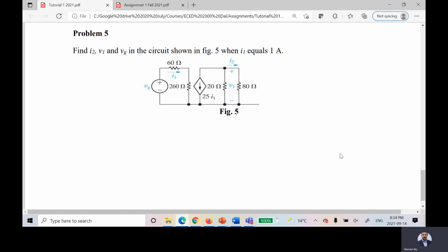And then for the conclusion, for example, you were working in the lab and you tried to measure the voltage across the resistor, or you were trying to measure the current in a certain branch. And what happens? You connected the ammeter in parallel. So what's going to happen to the fuse for the ammeter? It will blow out, which means the ammeter will give you 0 value. You have to comment on that. You will say, I got 0 value for the current because I made a mistake. I connected the ammeter in parallel and it was supposed to be connected in series. That's why I got 0 value. It doesn't matter to me if you got wrong measurements, but you have to explain why.